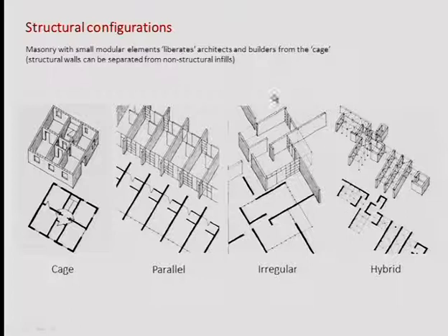This type of configuration has been used several times by Mies van der Rohe and by Frank Lloyd Wright to divide spaces. Instead of placing a door, you get a very wide space followed by a narrow space, and then again a very wide space and a narrow space. This is the way to create rooms and spaces without actually using a door or separating elements.